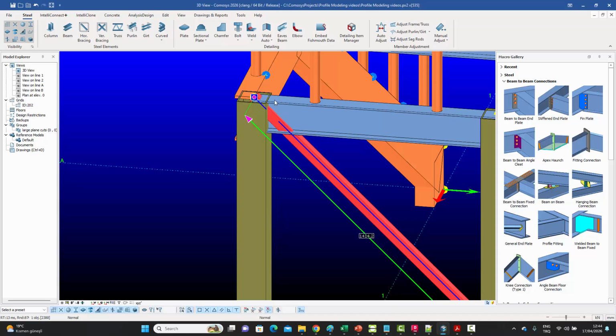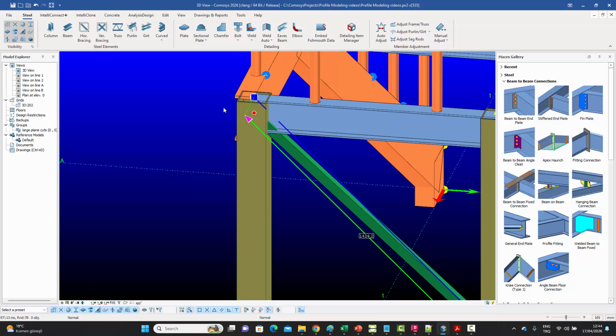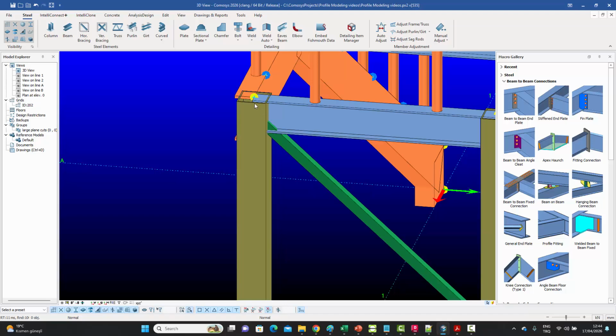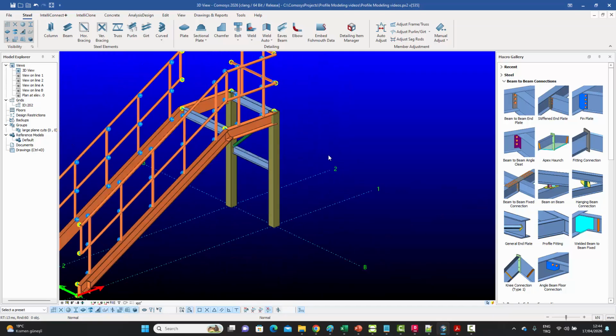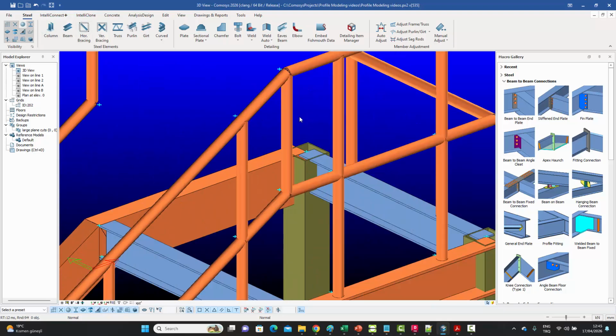And we know that the best way to do that is to use this blob over here, which only changes the offsets of one side. So we click on that, say Z minus 140, sorry, Z minus 70, I should say, like that. And now my definition is still there. I can see if I go to the line mode, it's still connecting to that point, but the 3D positioning has been moved down. So that's basically the point where I'm. One thing I forgot over here is this vertical needs to be deleted. That was copied from the other side.